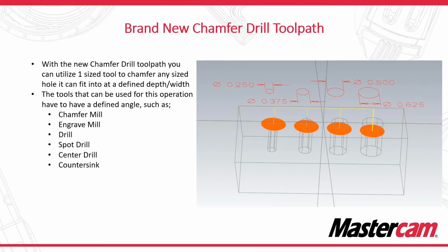And the best part about this toolpath is what it does is it'll be able to take holes that are different sizes, and based on what tool you select, it knows what depth to go for the exact width that you want to chamfer on the hole. So let's take a look at what that looks like in Mastercam.